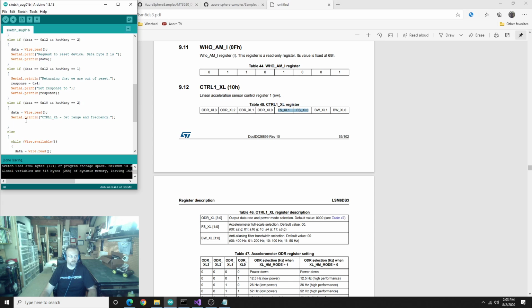So let's go ahead and try that. If data, we're going to shift by 2. And then we'll mask off. We only want these 2 bits, so we'll mask off by 3. I could do some later if you want me to walk through logical anding and oring and stuff. We can look at that. And we basically expect this to be a 2, right?